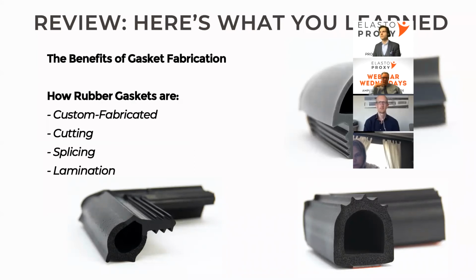So this is what we learned today. We learned that we can custom fabricate different shapes, forms of gaskets, different forms of cutting, different forms of splicing, and what to take into consideration when splicing. Again, your environment, what's going on around it, and the lamination of that.